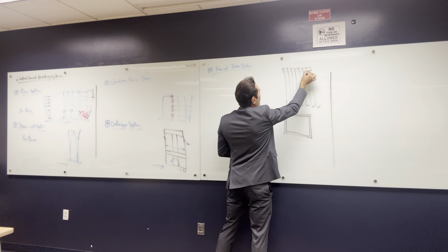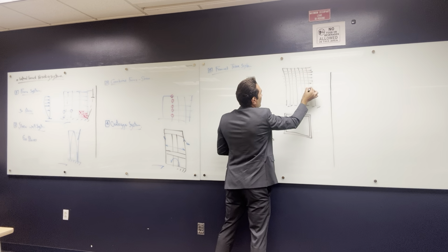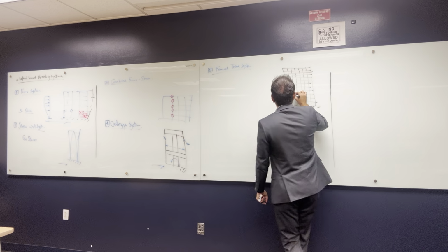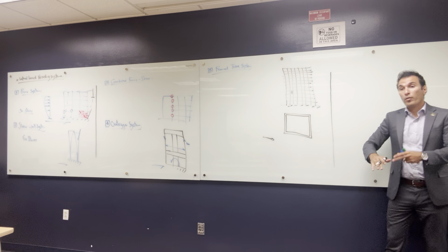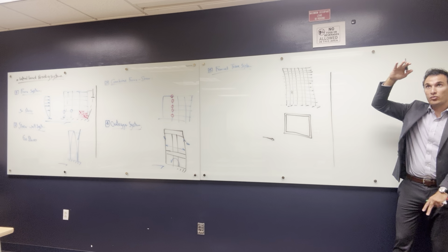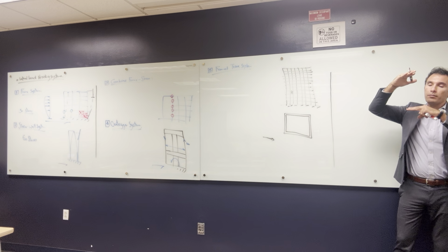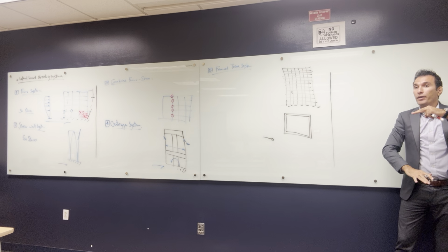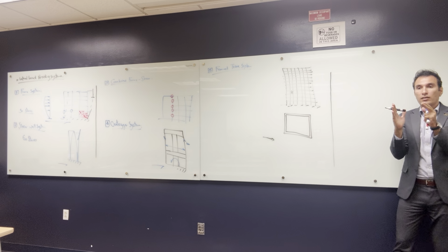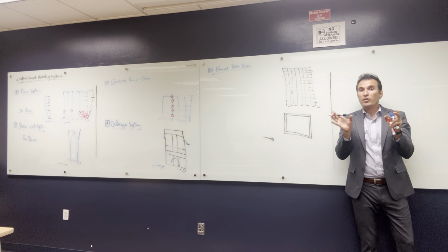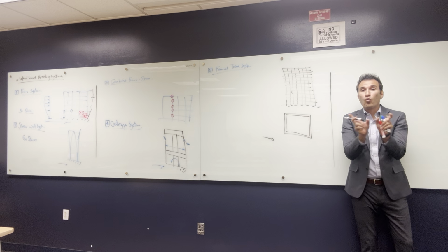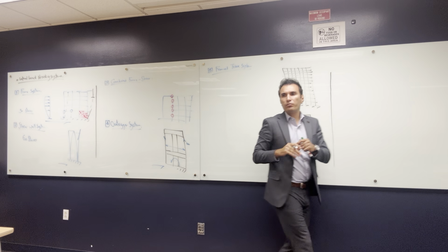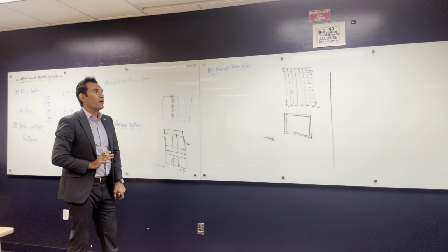Columns that are very closely spaced, something like this, all right? And they only have these openings for the windows, right? We make a very deep beam, like let's say we have a 3 meter story height, and you make the beam 1.2 meter depth, and you only leave 1.8 meter as an opening. And the columns are very closely spaced, like you have 1 meter by 1 meter, maybe 1.5 and 1.5, and they have a spacing 1 meter in between them, or 2 meter in between them. So you are making it very, very close to a shear wall. So that's the idea of the tube system.